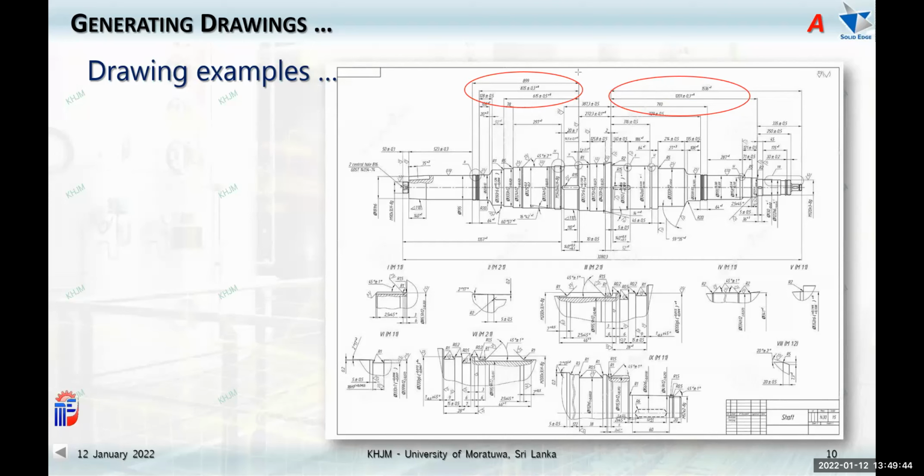So you refer to this end and then start dimensioning to this point and then to a different point and also to another point. So depending on your design attributes and design requirements, sometimes you have to use it like this. If you start dimensioning from a corner, we call it the continuous dimension. First feature, second feature, third feature, fourth feature, and so on.